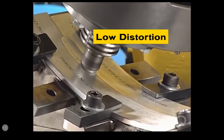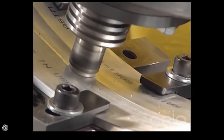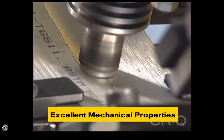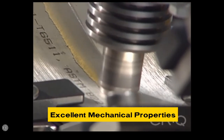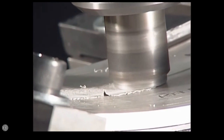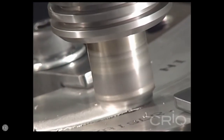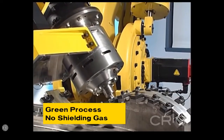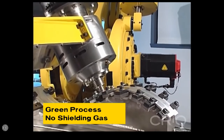FSW requires a large amount of downforce to plunge at the start and maintain tool orientation, so heavy-duty tooling is required to hold the parts in position. The M900iA robot is an ideal solution for this task. Its servo-controlled speed, accuracy, and heavy payload capacity ensure the optimum downforce is applied while producing high-quality welds.